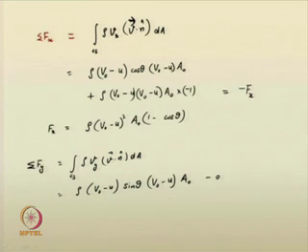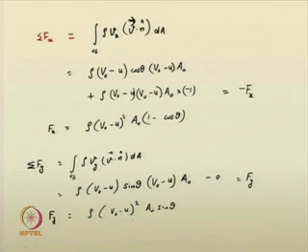So, this is 0 here. This is the same as f y now, because we have assumed velocity in the positive direction of y. So, the force will be the same. So, you can write f y is equal to rho into V 0 minus u squared A 0 sin theta. Fine. So, this is for a single vane.